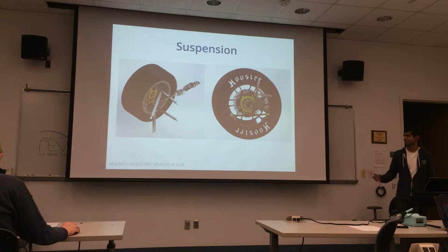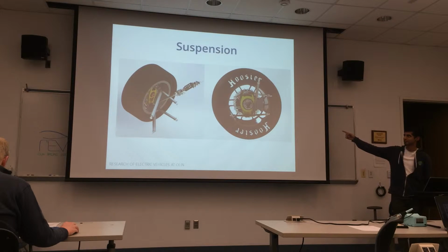And then the suspension subsystem. Suspension is actually where maybe the bulk of the design of the car goes, just because it's so important, and there are so many components to consider. It's everything attached to the wheels. On the right, you can see our rear suspension from last semester, and on the left is our front suspension. The key difference is there are some extra linkages for steering in the front suspension, and you'll notice there's this giant hole in the middle of the rear suspension, and that's for actually powering the rear wheels, because we need to be able to drive with them.